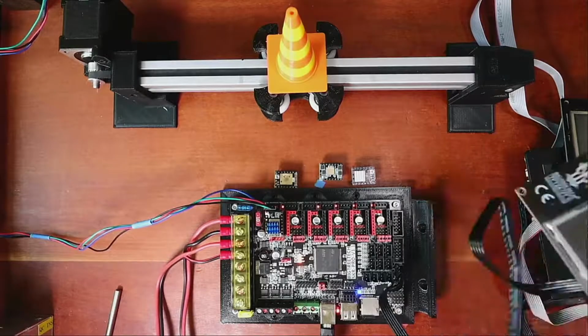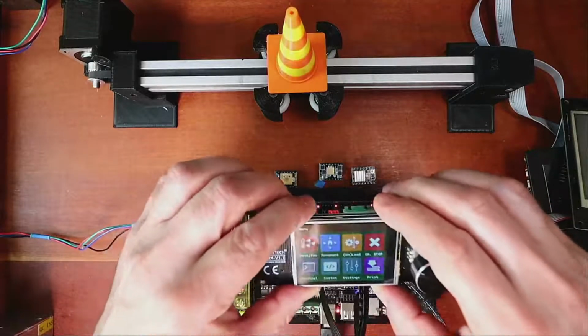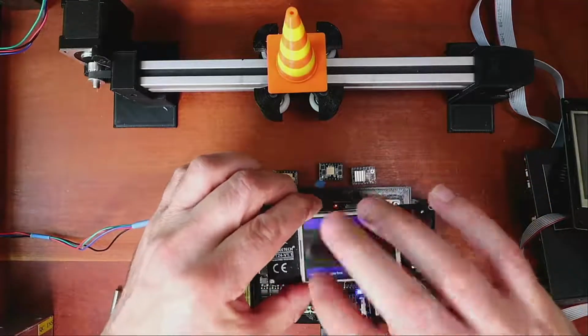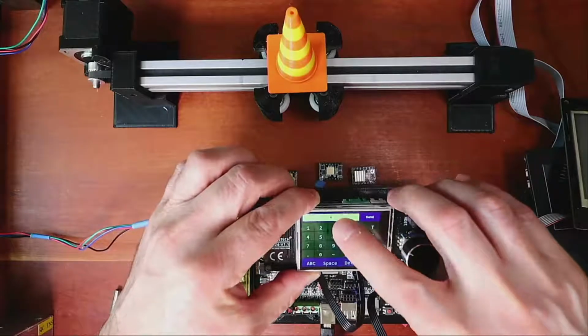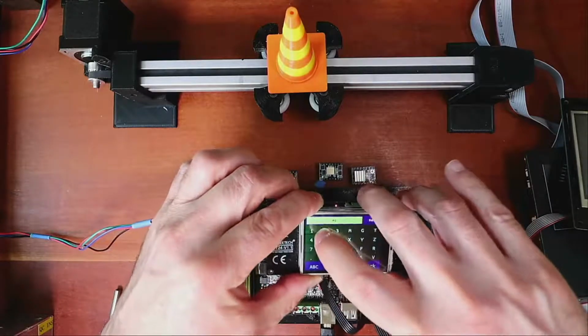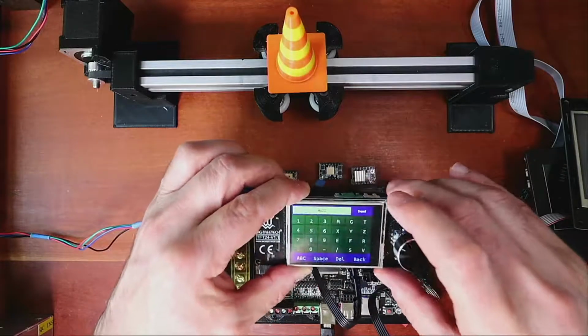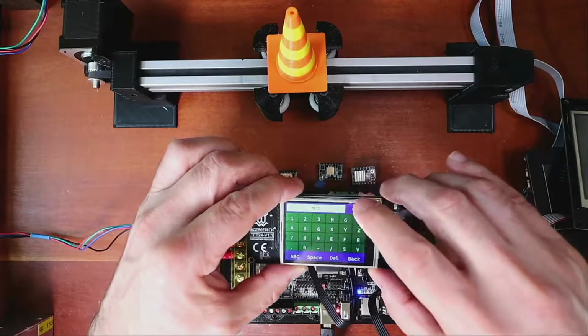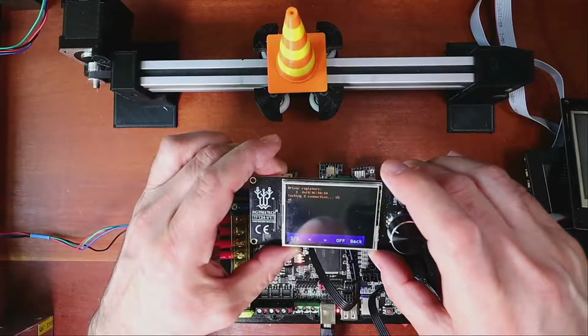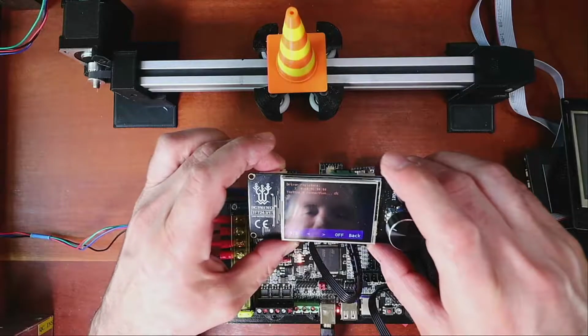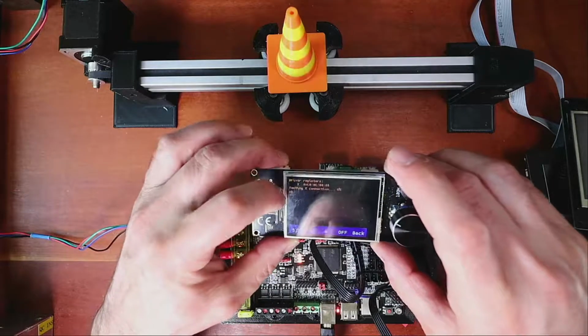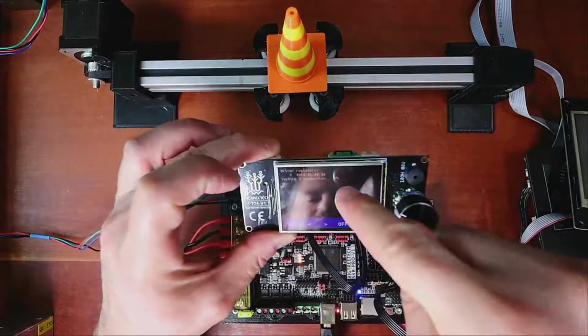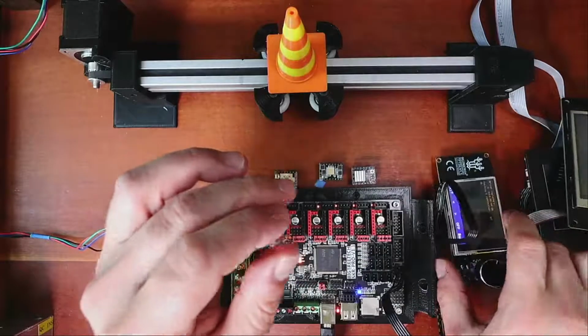So when this comes up, what he's talking about is on the screen they have a terminal window, and you can go M122 and you can send it and it'll give you a readout in theory. There it goes. So that kind of went by really quick, but that was the stepper it was talking about, being this one being okay. That's the same thing I do in Pronterface.